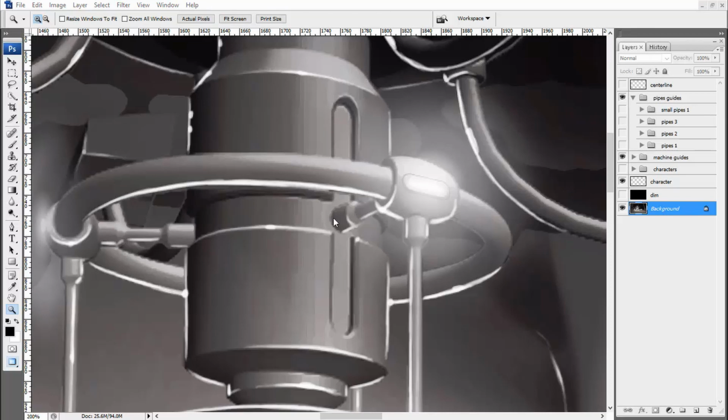Looking at the edge of this groove, it's actually quite close to the edge of this cylinder I've just made. And another thing to notice is the curvature of the top part of the groove here. In other situations, I would duplicate the cylinder I've just made and then place that up at the top and then use that as a guide to start cutting the central column. But in this case, I don't think that'll be quite round enough. For this strut, I think 8 sides for that cylinder is enough. It's not a very prominent object.